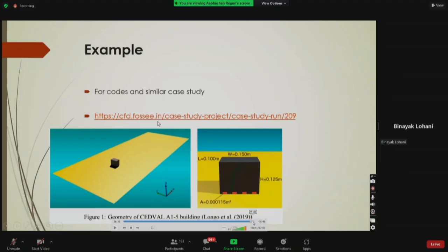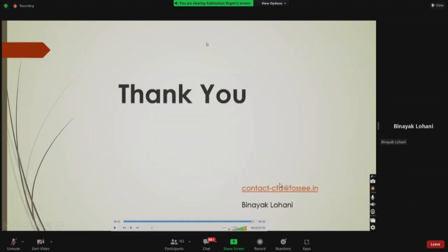I think most of you are wondering how the velocity field will come out, so how we'll get the velocity data to run the scalar transport foam solver. For that, first of all, you will need to solve using another solver, for example simpleFoam or potentialFoam, without any scalar term in it. It's a simple steady state case. First, you run that with the same geometry, then extract the data from your last time step and put that in your initial conditions in the next simulation that you want to run. That's how you will get that.